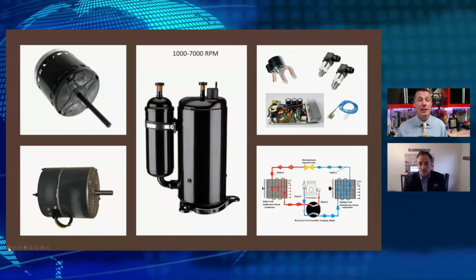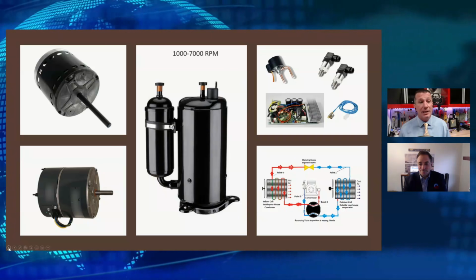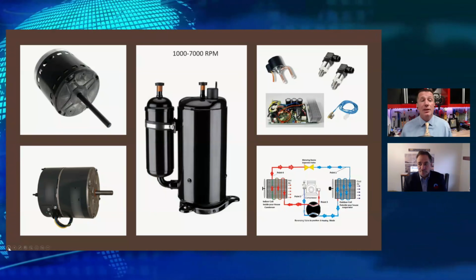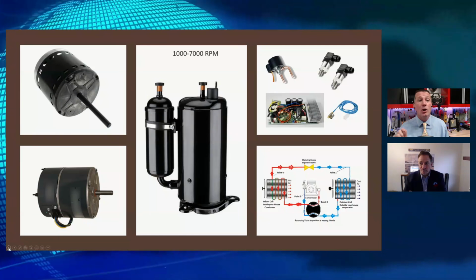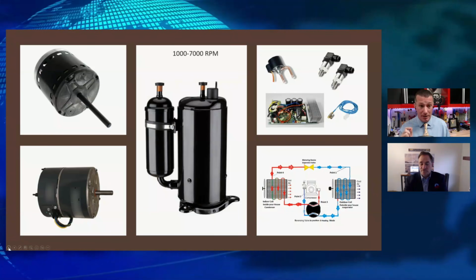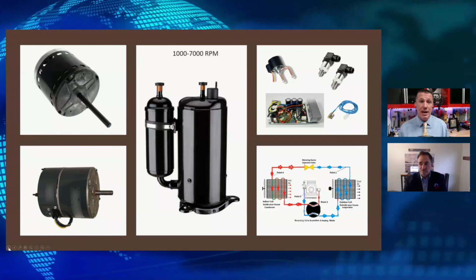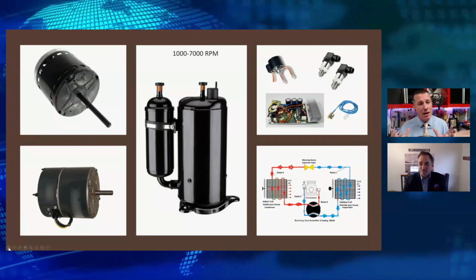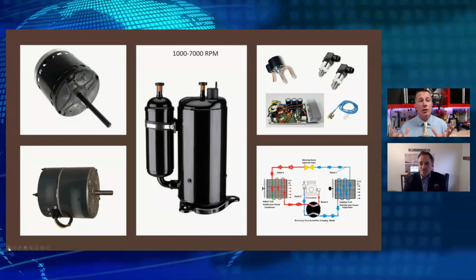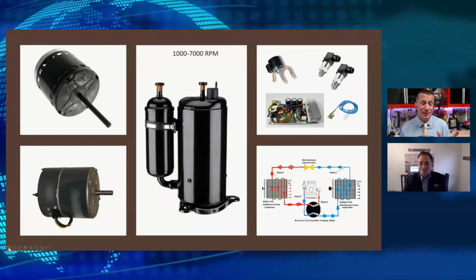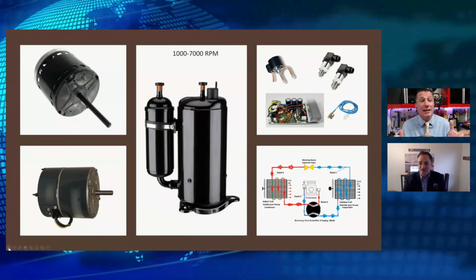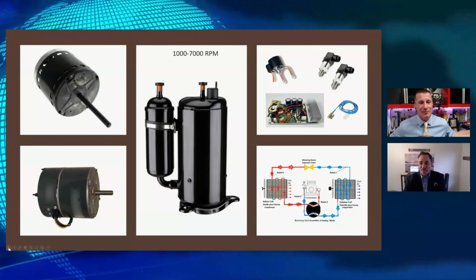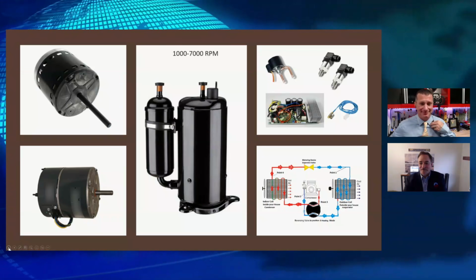So there are a lot of thermostatic expansion valve controlled inverters in the field. I have even seen some that have variable speed indoor motors, variable speed outdoor motors, variable speed compressor, and thermostatic expansion valves. So we have a combination. That's why we say they're not all created equal. They are created by the manufacturer for a specific market and a specific range. So what is that range? That's where you have to do the research to find it.